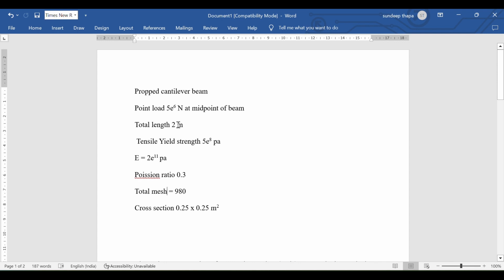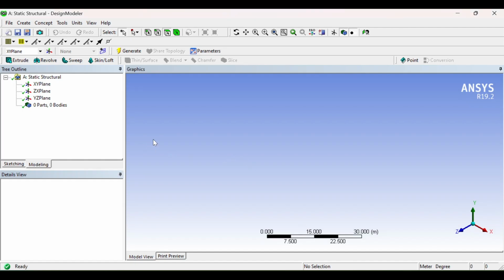If we performed structural analysis using these dimensions and a 3D model, that would be really expensive in computational resources, and it is an inefficient way to do a structural analysis of this length. So what I'm going to do is create a line element.